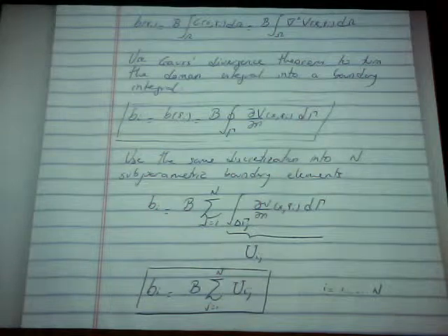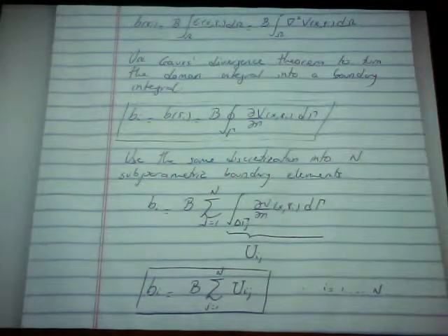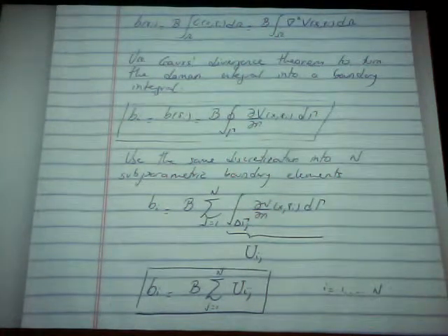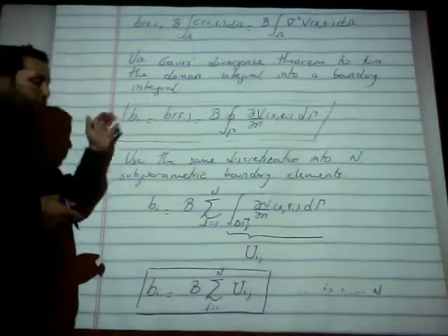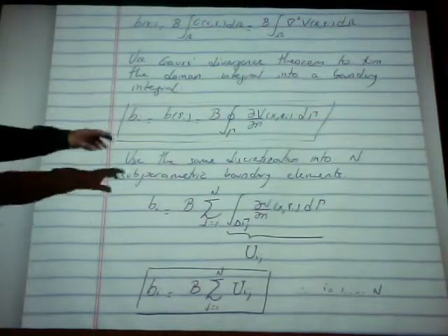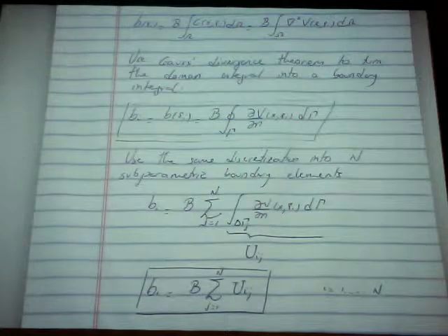And that's it. Now all the information is on the boundary, and the boundary integral is solved the same exact way we solved all the other boundary integrals for g and h, for which we already have the structure in the code. We already have the mechanism, the integration routine, the discretization. We don't need to do anything else, okay? You just create a separate routine, and that separate routine is just going to call another fundamental solution, which is this v, which is that r squared over 8i and so on.